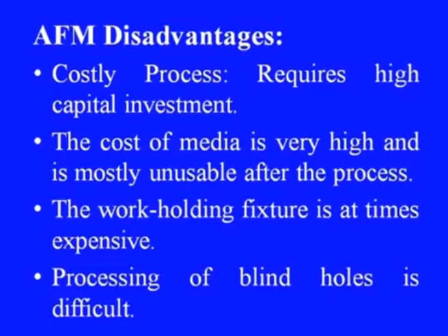Then there are certain disadvantages as well. Basically, this is a costly process. This requires high capital investment. The cost of the media is very high and it is mostly unusable after the process. Recently, some reusable media have also been developed that we will discuss in subsequent discussions. That is again a development of IIT Roorkee. The work holding fixture is at times expensive. Processing of blind holes is difficult in this process.